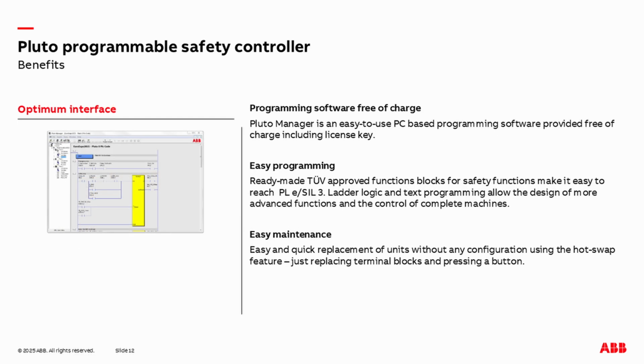Here is the programming interface that you can see in the picture to the left with the yellow block. These are ready-made, TÜV-approved safety function blocks. Comes with a complete description, easy to understand and integrate in the ladder logic. The program itself, Pluto Manager, is ladder, and it's provided free of charge. All you have to do is request a license key, which is also free of charge. Easy to maintain. I'm not going to deep dive into it, but hot swapping is to a certain degree possible.